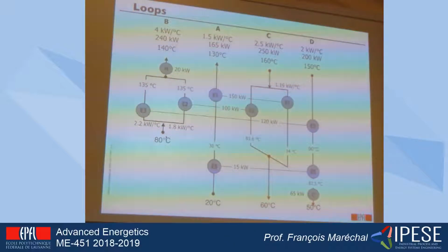So in addition to playing with heat loads to reshuffle the heat load repartition, I can also play with the flows in order to reduce the penalty of the temperature differences. Okay? So this one is not impossible, but has smaller delta T minimum than the one that was expected.